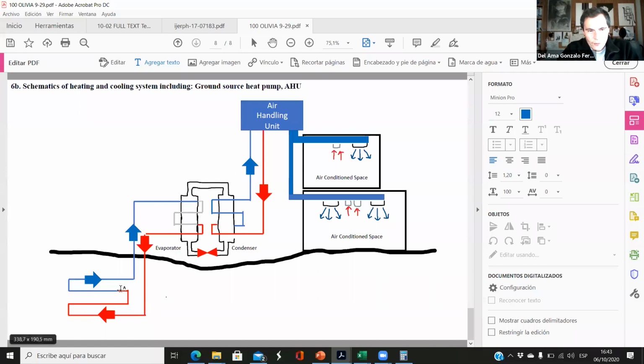We know that we have those boreholes or this buried loop, whatever. It can be shallow or it can be deep. Shallow, it's buried like 6 to 10 feet, and the deep borehole is around 200 feet. Anyway, the deep one is more effective, but the shallow one is cheaper. So it's up to the client, the company, the architects. We have to deal with it.